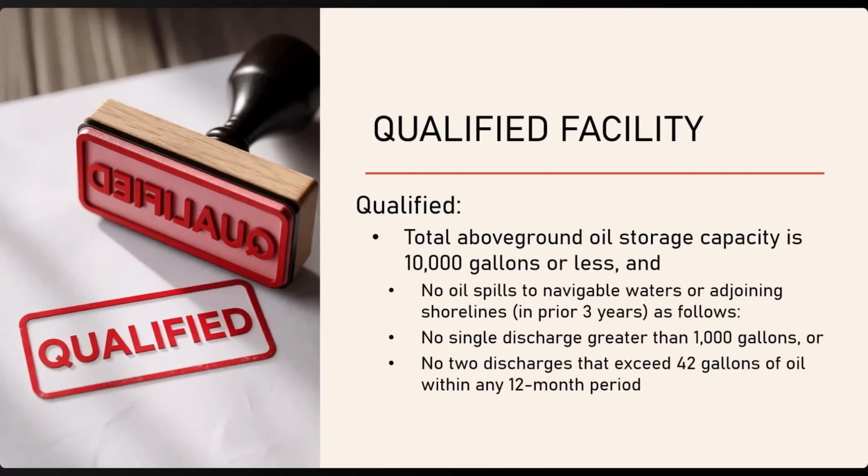In order to meet the definition of a qualified facility, the facility must meet certain criteria. The first hurdle is that the above-ground oil storage capacity aggregate is 10,000 gallons or less. If yes, then the next test is, in the 3 years prior to needing an SPCC plan, there has not been a single discharge of oil to navigable water or adjoining shorelines greater than 1,000 gallons, or there has not been 2 discharges exceeding 42 gallons of oil during any 12-month period.